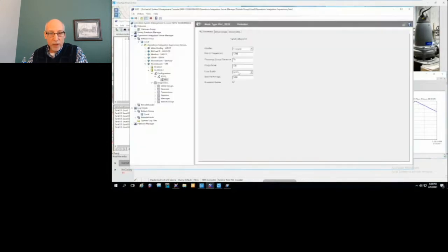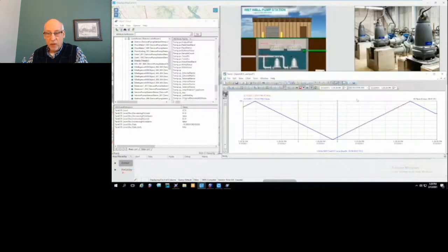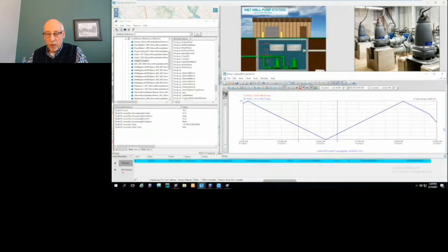So let's go increase that rate. I'm going to go back into my simulator, and we're going to change the slope of that line, change that angle. If I look at my trend here, you're going to see it's starting to rise quicker than it was before. I changed the angle of the line, and what it did, it went into a rate of change alarm. It went to the downward slope rate of change alarm just happened. You can see the color coding on the actual trend itself.